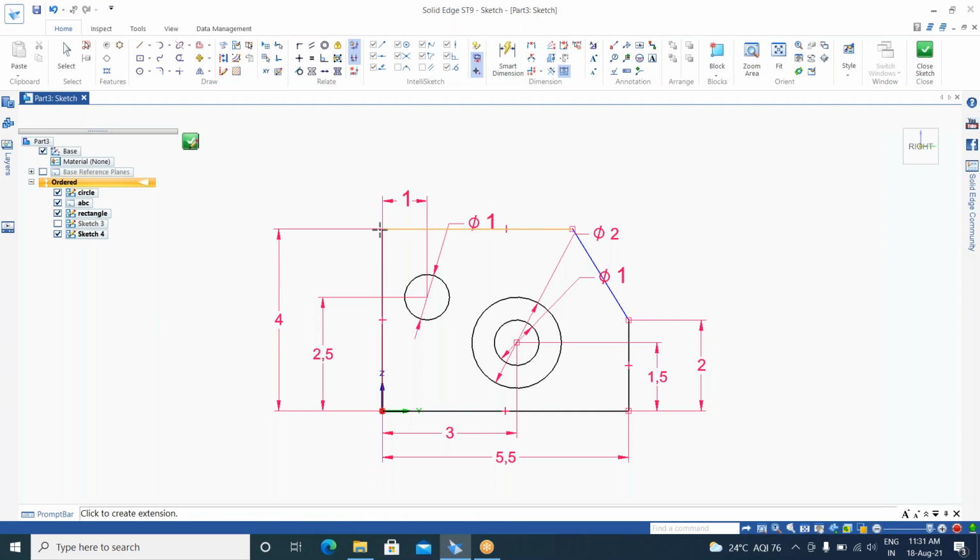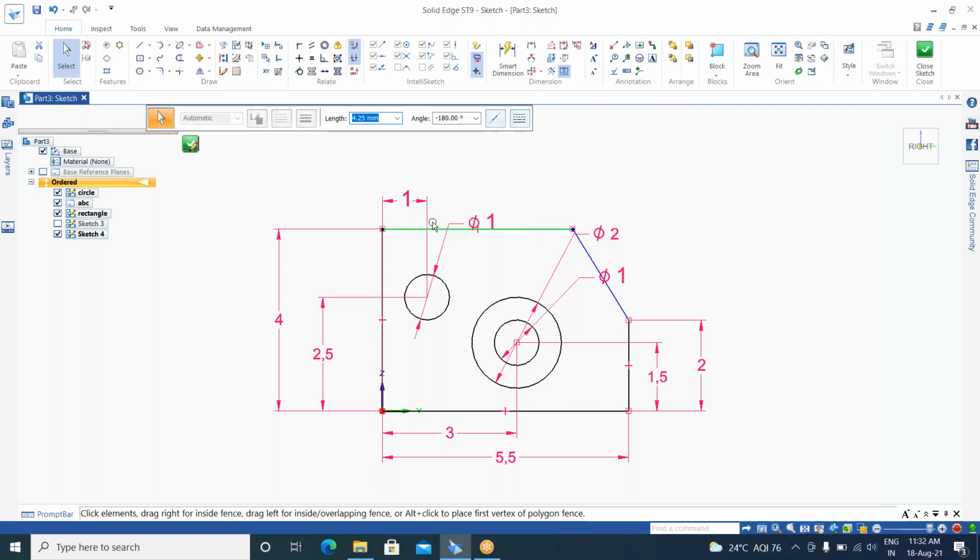Up to where I need to extend, we have the reference of a 4 mm line here, so I'm going to extend this line up to here. If we don't have any reference line, it is not going to extend. We must need an extension line. Now see, only the single line. Previously we completely split the line and removed the other portion, and without making it an attachment of two lines, we are going to make the single line extend up to the end point here. Like this we can extend a line in any direction along the direction of the previous line's existence.